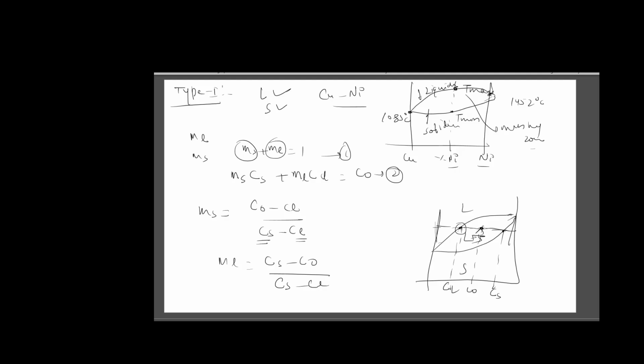And if two materials combine together and produce a single phase in the solid state, it is called a solid solution or solutionizing. Mushy zone is a characteristic of the particular alloy. The larger the extent of the mushy zone, the lesser will be the fluidity of the liquid metal, and hence more variation will be there in the properties of that alloy.